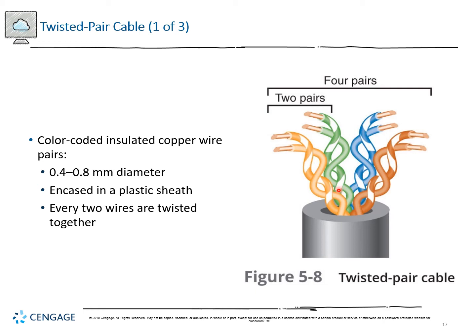Now imagine that this helical twist remains the same as we go up the cable. So at every point, if we rotate the cable and look at it, the cable overlap should be at a 90-degree angle. That allows us to avoid the cross-contamination of the signals because they're constantly running at 90 degrees to one another, which means it's a minimum contact area.